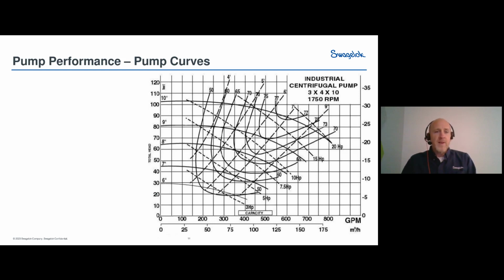All right, so let's take a look at pump curves. You've probably seen these before. They look a little bit different if you're in Europe or maybe in Asia. But here in North America, you're going to see these combined pump curves. And when we're looking at where our pump is operating on the pump curve, you've got the pump head on the left, and you've got the flow rate along the bottom.